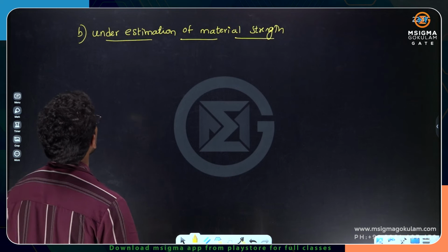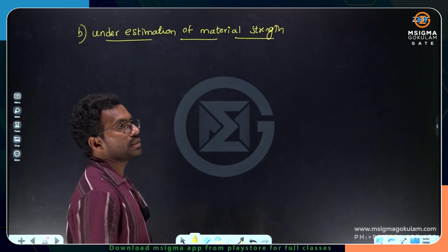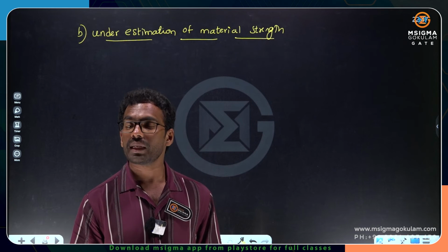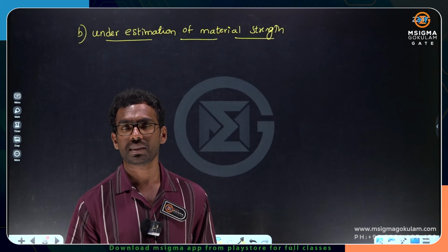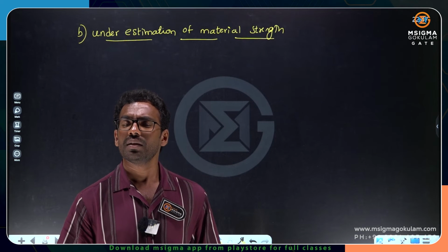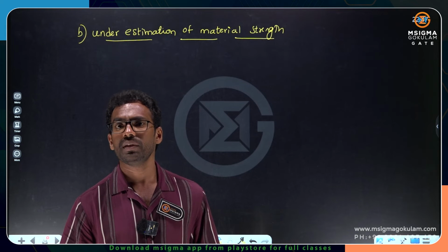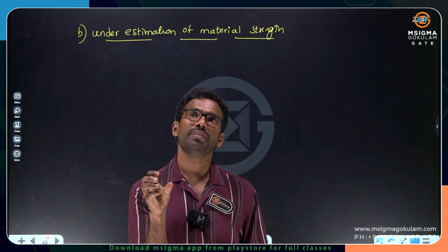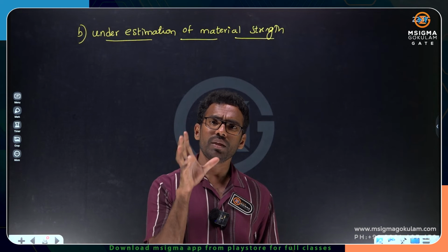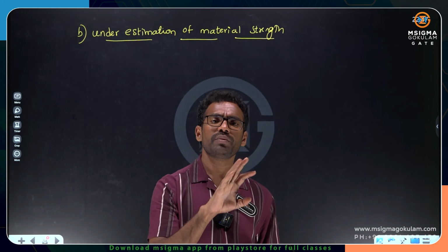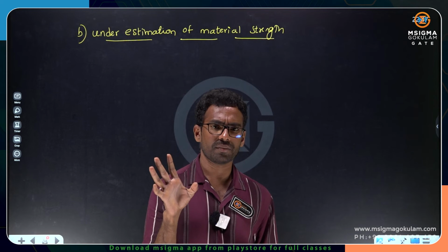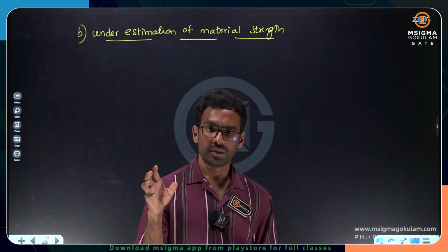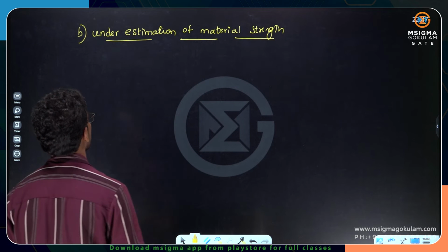So, what our code is saying is that whenever you apply some stress on a material, that stress should be in such a way that it should not reach the full capacity. Whatever the full stress capacity is, the material should not undergo that much stress. If it undergoes that much stress, it fails. So listen, our limit state based code approach is saying that in no case should our material fail. That is the major concern. That is the intention of the code.